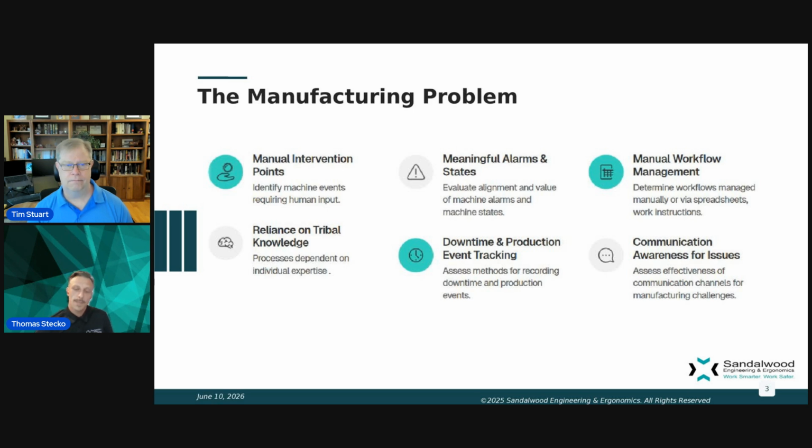If we have a robot that the manufacturer states needs its oil changed every 8 months, but you're monitoring oil pressure, oil temperature, etc. And if the numbers look okay and the color or the performance of the robot looks okay, you might be able to extend that, right? It just depends. So yeah, doing something with your data, not just letting it sit there.